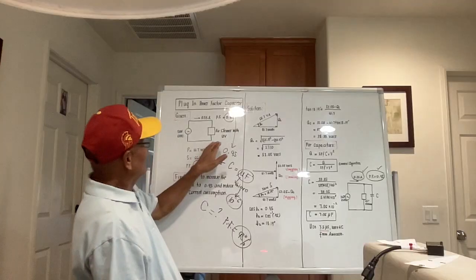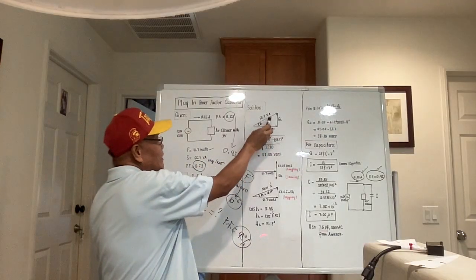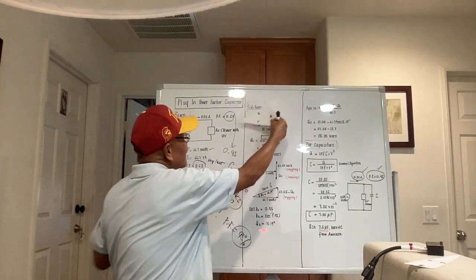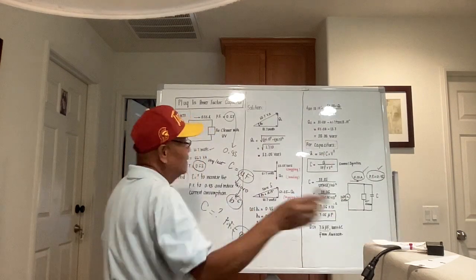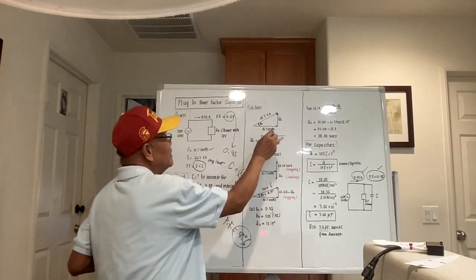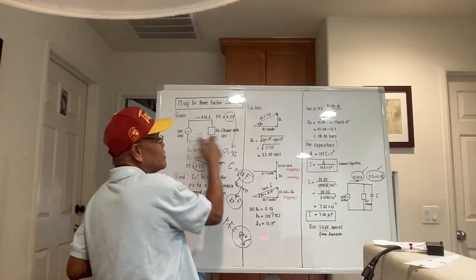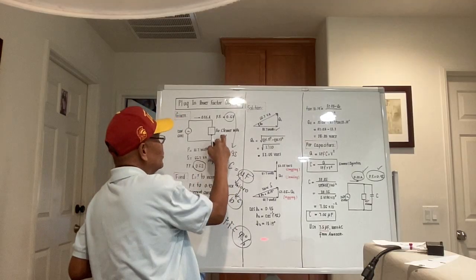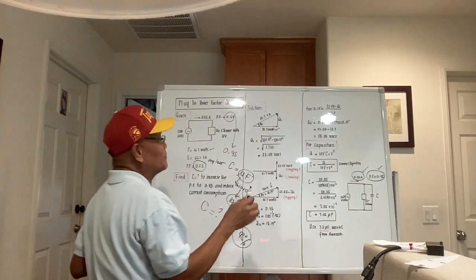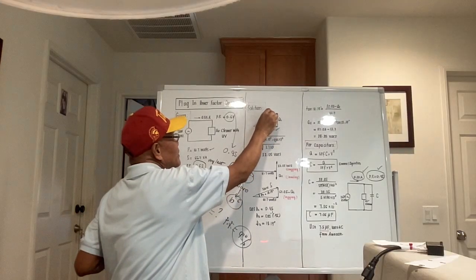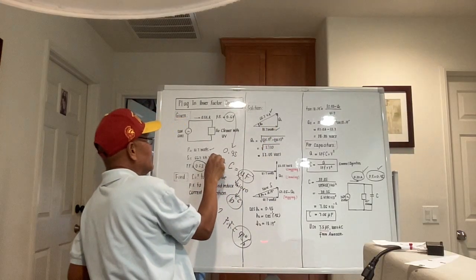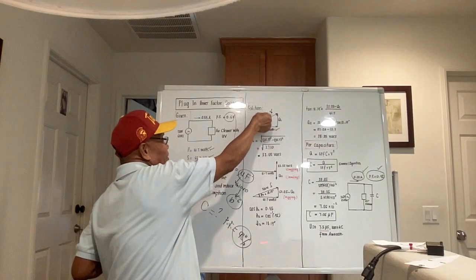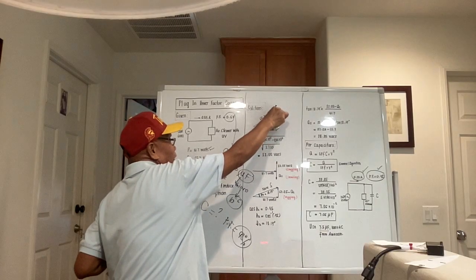So for the original circuit here, this is the power triangle. The measured true power of this one here without the capacitor is 41.7 watts, this portion. The total apparent power is actually the hypotenuse. It is 66.7. It is 66.7 and 41.7. This is known. For the meantime, we do not know this value here.